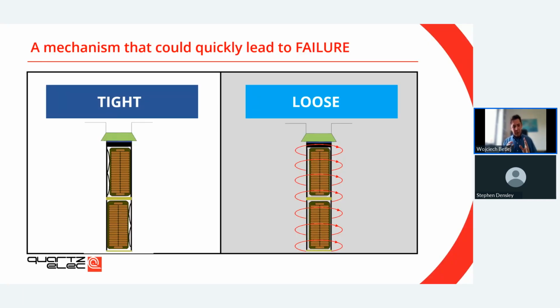So let's think for a minute about this problem that large generators will suffer from. What you see on the screen is an example of the slot cross-section of the stator. What you see here, and let me just find a pointer. There you are. What you see is the core, you have the stator wedge, then you have your top bar, and you have the bottom bar. And you can see clearly the difference between the left-hand side and the right-hand side.